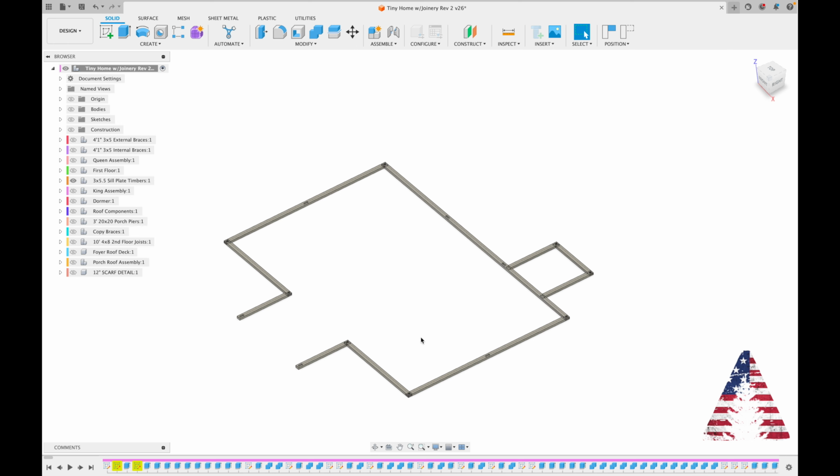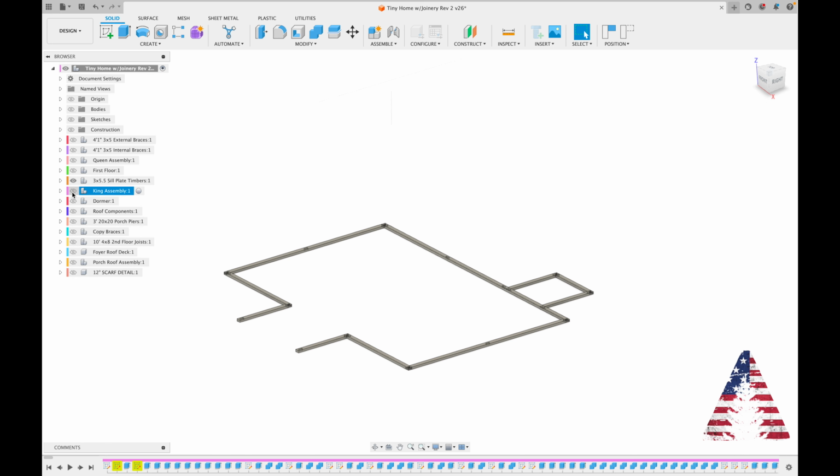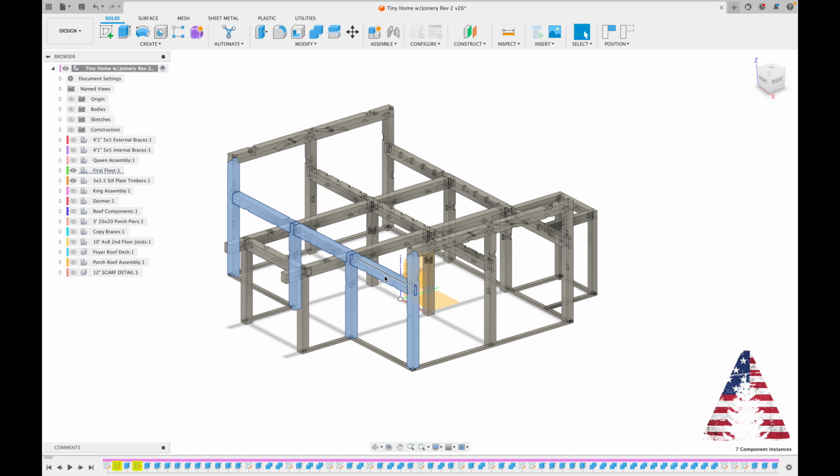So all this will have to get assembled, and then we can get our first floor. We would test fit these 4 posts, these 3 beams, make sure we're all square and plumb, and then we can raise this. So we can raise this one frame section and move on to the next. And in our case, we would move to this back wall.